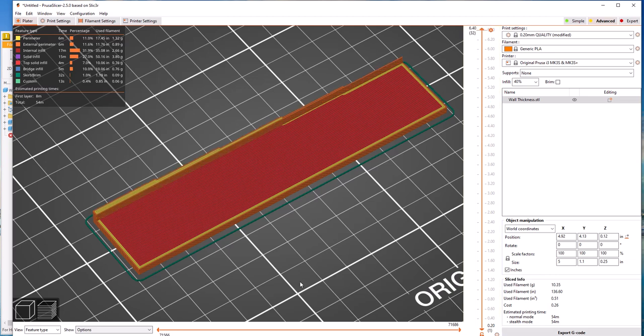So far we've talked about wall thickness and how you can change the perimeters and how that might affect the infill of a wall from a box, as we saw here. We looked at top and bottom layers. How many solid layers do you want, or how many do you need? If you're trying to make a really strong part, then you probably have a lot of walls and a lot of floors and ceilings. We also looked at our infill, how we can change the percentage and the type of infill. And by doing the slice now, you can quickly and easily see what those look like.